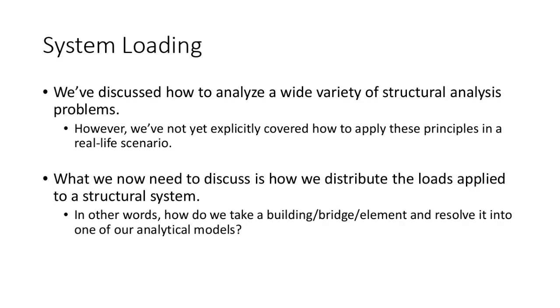Well, I think we've beaten that topic into oblivion. In other words, handling those models was really the main focus of this class. But what I want to talk about today, and again, you'll see how this puts a bow on things, is how we take those mathematical models and apply them in a real world scenario. If I have this frame, how do I turn it into a simply supported beam with a uniformly distributed load? Because once I do that, the next step is, okay, now I have a model I can analyze. I can determine the shears on that beam, the moments on that beam, the deflections on that beam.